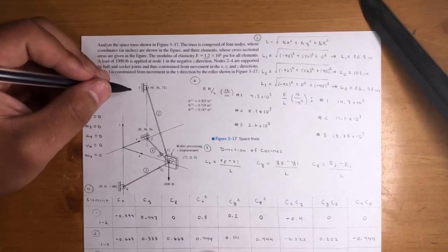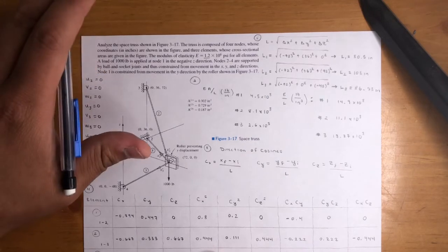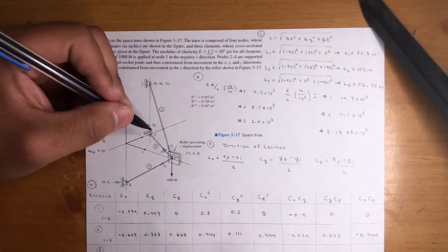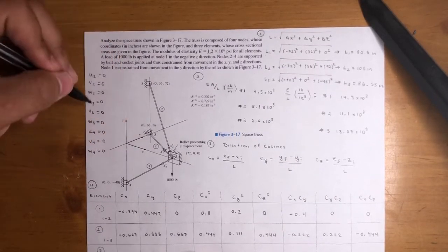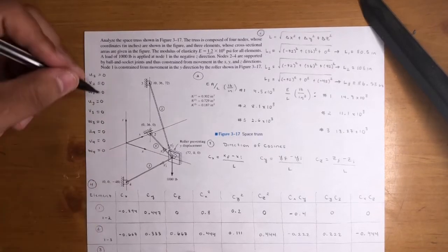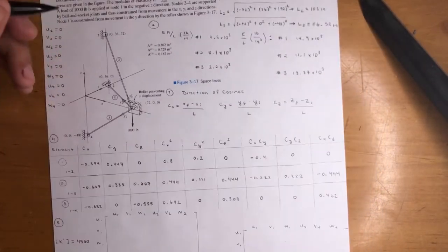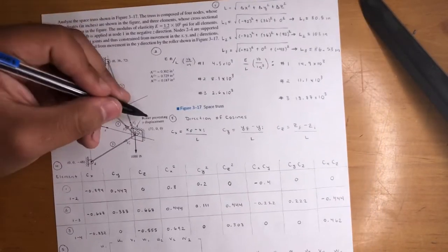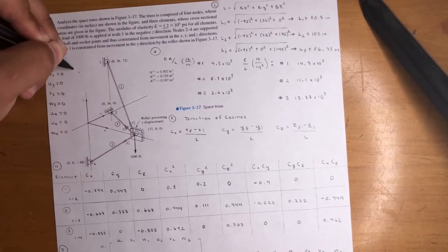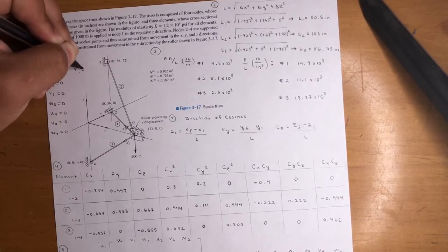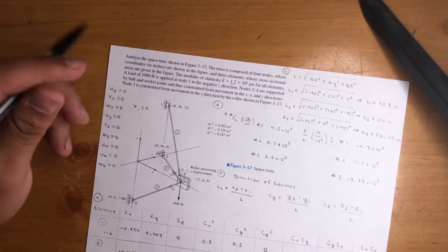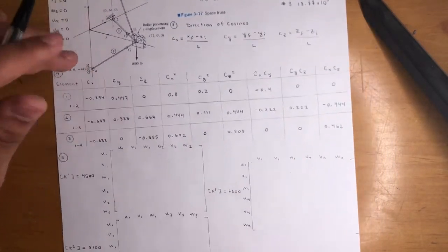Sorry, I'm getting a little sidetracked. But point is, you have those 3 reactions, okay? And it can't move in those directions. So you have these boundary conditions: U2, V2, W2, 3, and 4, they're all 0. So that's going to make our problem a whole lot easier. And there's one more thing. They also said roller preventing Y displacement. So that means at node 1, the V direction or the Y direction is also 0. So we have these 10 boundary conditions, and it's making our problem really, really easy because they just cancel out.